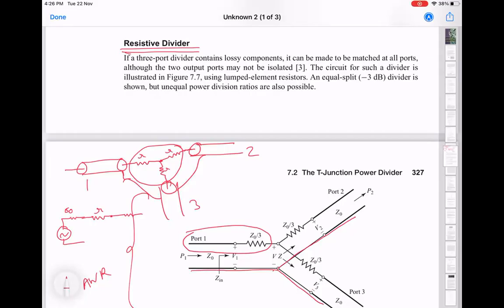This is small r, and then that would be 50 ohms. And there'll be another one here, r. This will also be 50 ohms. You can connect these. This is all ground. So now it looks like our conventional voltage divider, but of course there are some extra resistors. But this is all in order to maintain the matching of the overall system.